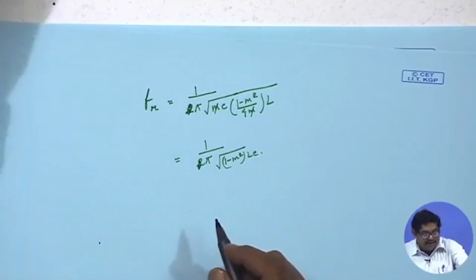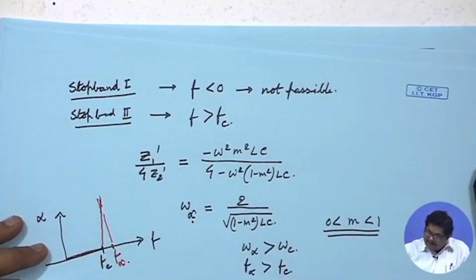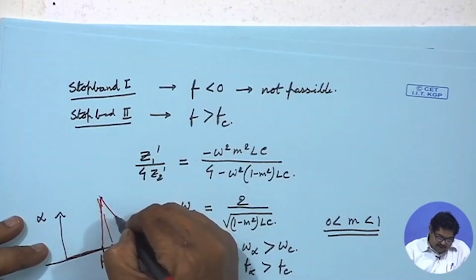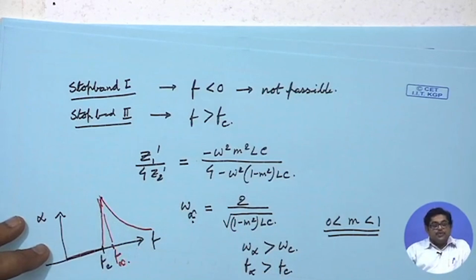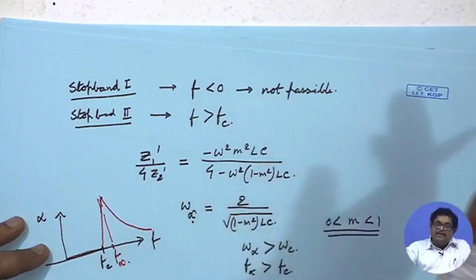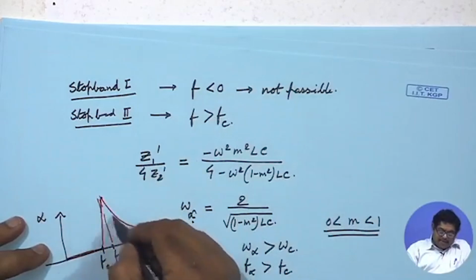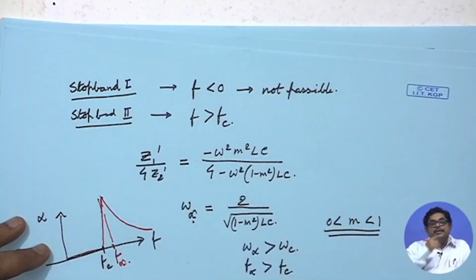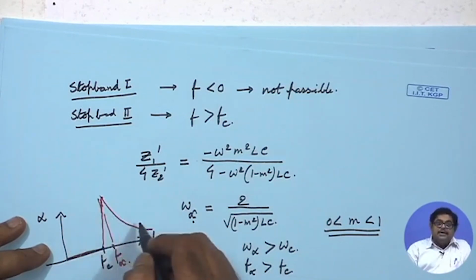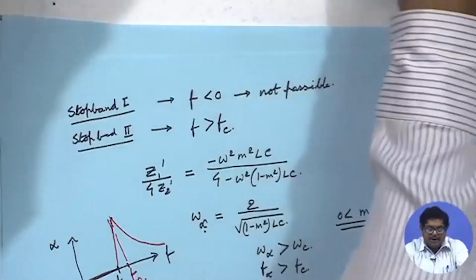But the price I pay for that is unfortunately this thing, that after f infinity the curve is like this. So, alpha again falls. I also want that at very high values, or all further values, the attenuation should be high, but you see attenuation is falling due to this m-derived section. So, I can solve one problem, but in constant k this was not a problem. In constant k it was going exponentially.